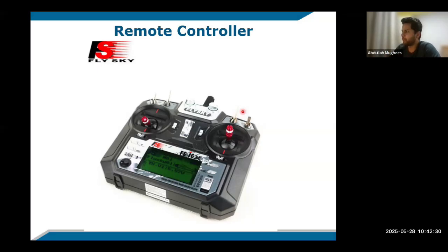For example, you just flick this switch downwards and your drone will land, or maybe you flick this switch downward or upward, your drone will flip, or your drone will make a circle, or it will just take off from one point and go to another point and land, or perform an autonomous mission that you pre-planned using that plan tab in the mission manager that I showed you.